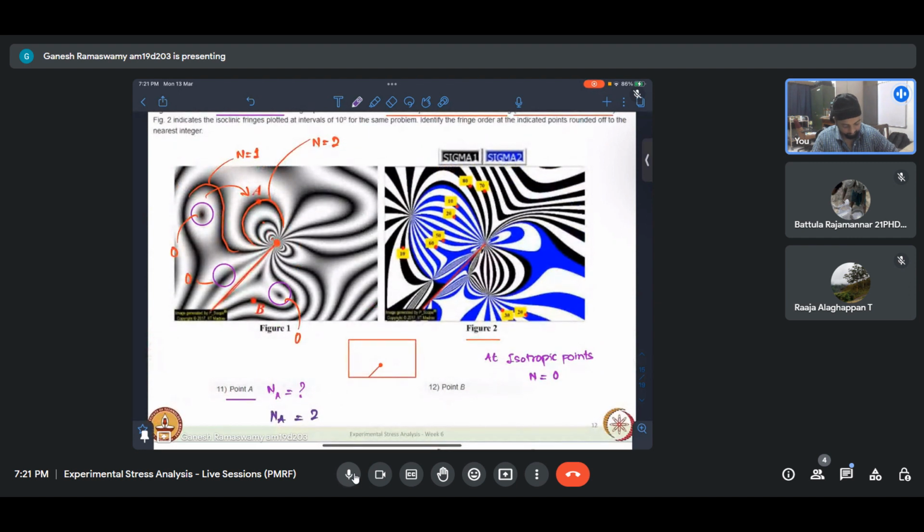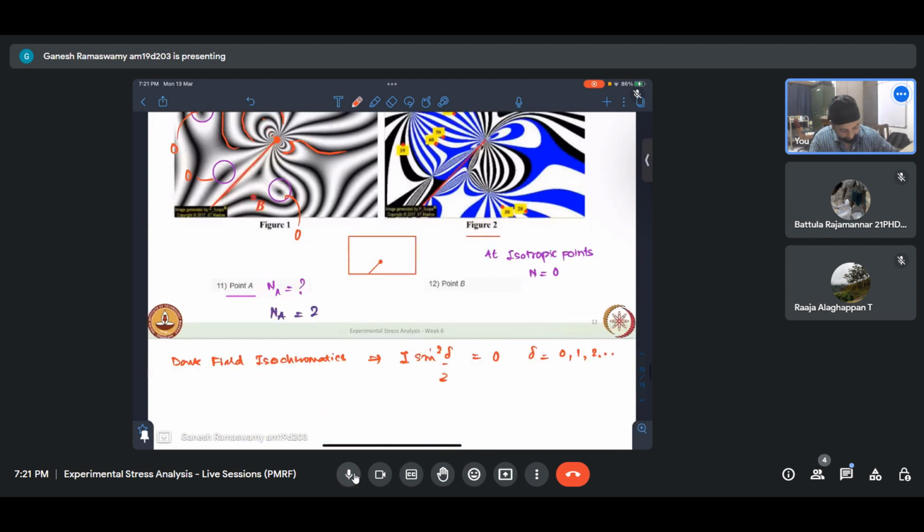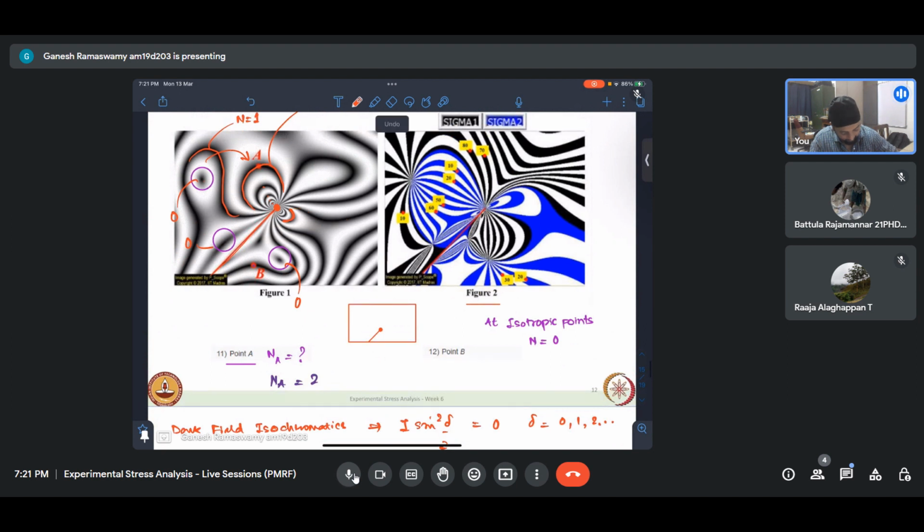So we know if this is 1, we can see that this is one fringe. Then the second fringe is going something like that. It would have merged here if it was loaded a little differently, but the pattern still holds. My fringe gradient direction is like that.